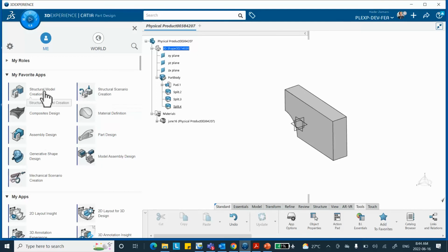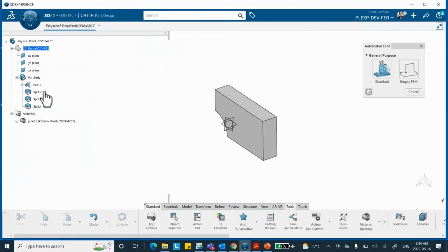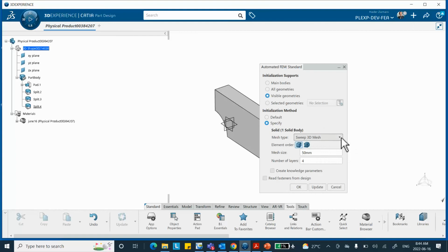Let me just first do the meshing. This is the basic stuff that we are doing, so I use the standard one. It says, do you want the swept mesh? In other words, a very nice four-sided element swept? Do you want the pyramids, stuff with the pyramids and things like that? The standard in Catia, you can do it like that. You see that? Octree tetrahedral element. So these are inherited from Catia, okay? But we're going to do a nice swept mesh that is not easy to do.